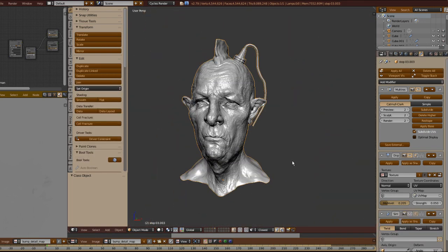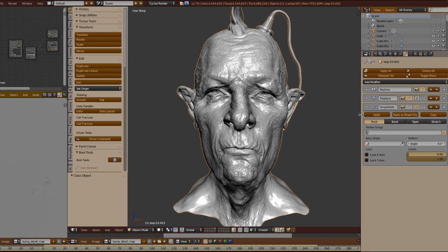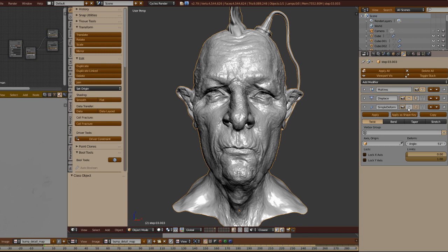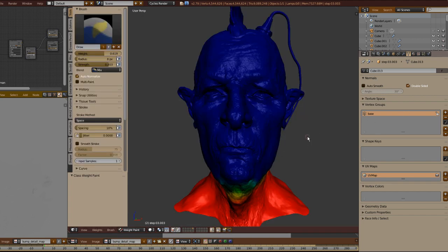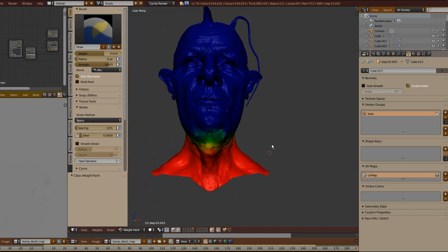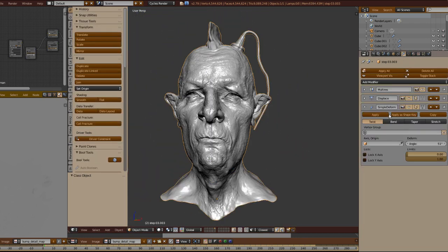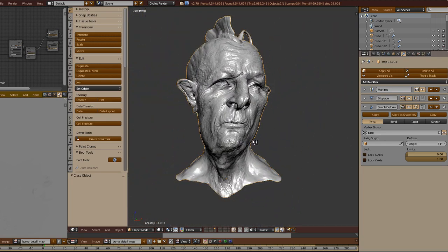The last step was to deform the character's face by taking advantage of the modifiers. Was it necessary to do this? I do not know, but once again the system allows me, and I was able to test. Why not explore the possibilities, right? For this, I first created vertex groups. Then, I added another modifier called Simple Deform, and I configured the modifier so that only the vertices of the vertex groups could influence and deform the part I wanted, which in this case was just the face.